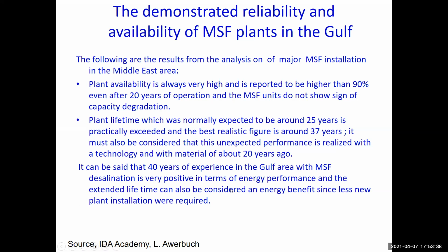Talking about the analysis and evaluation of performance of some of the MSF plants in the Middle East, the plant availability is very high. What does availability mean? It means look at the number of hours over the year where the plant is up and running. This is more than 90%. RO technology cannot have this kind of high plant factor. That's something which is associated with MSF.